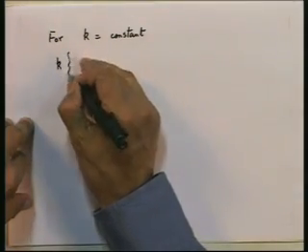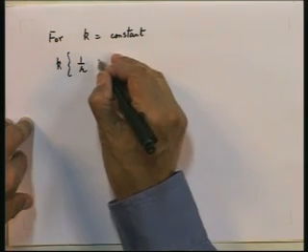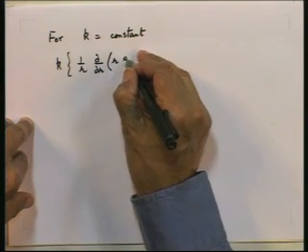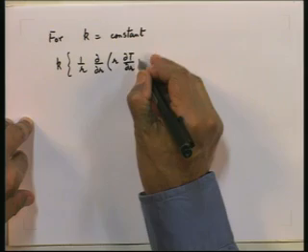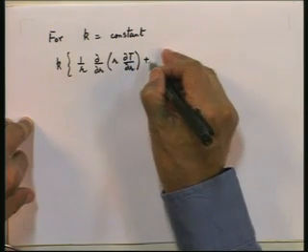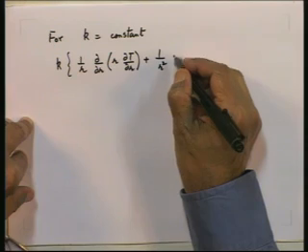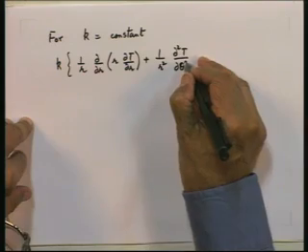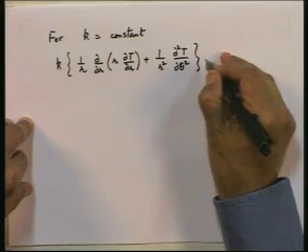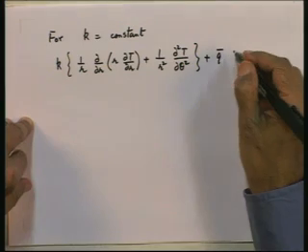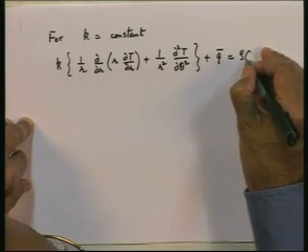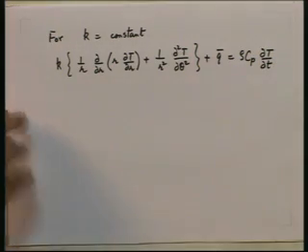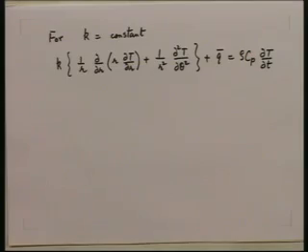So, k multiplied by 1 by r d dr r dt dr plus 1 by r squared d 2 t d theta squared plus q bar will be equal to rho Cp dt dt. This will be the differential equation that you will get with a constant k.